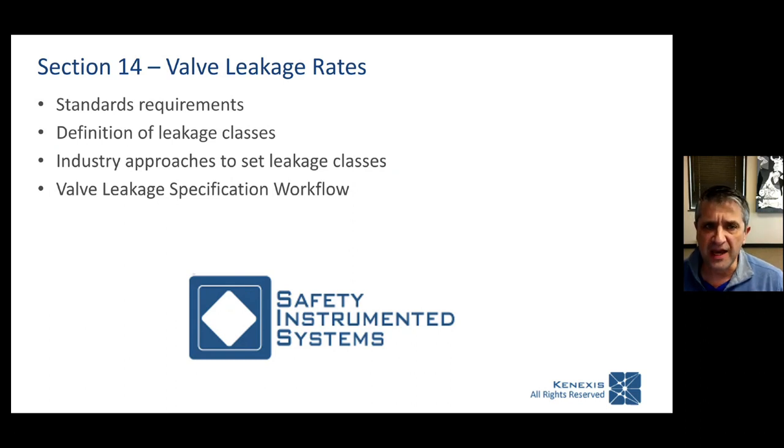Well, if you say that everything needs to be tight shut off, it actually needs to be tight shut offs. So you need to buy special equipment that is rated for tight shut offs. But even worse, you need to perform ongoing maintenance and testing to confirm that those valves stay tight shut off over their entire life cycle.